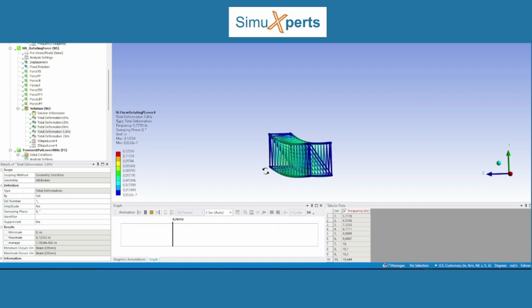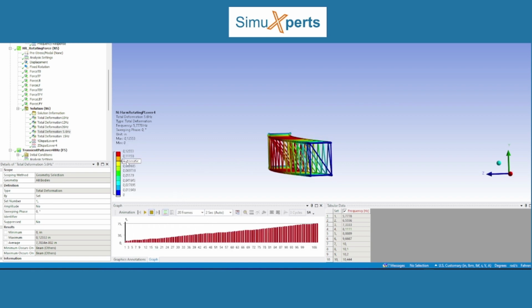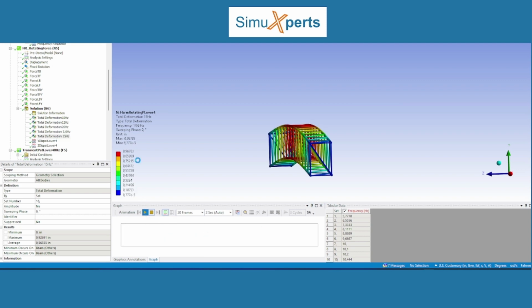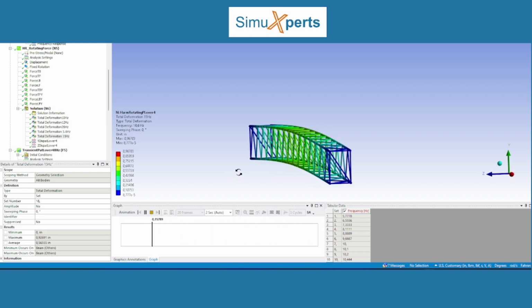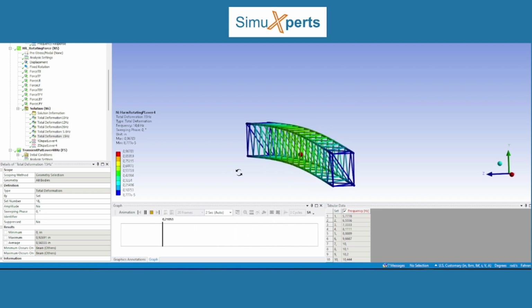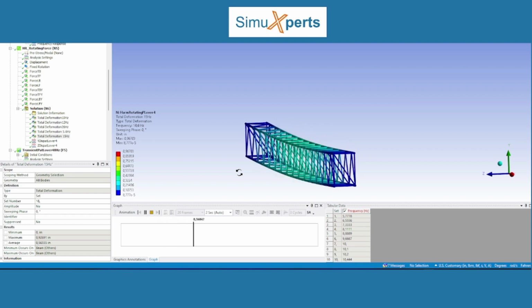Now let's look at a second deformation pattern. For this one at 5.8 Hertz, we see a motion that's mainly in the Z direction. We're now going to move to 15 Hertz, which is slightly above the first mode in the strong axis direction. So this first mode is at 14 Hertz. What we see here is clearly a displacement that's slightly in the Z direction, but mainly in the Y direction.